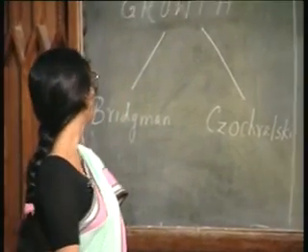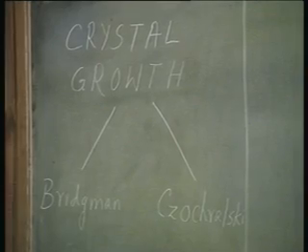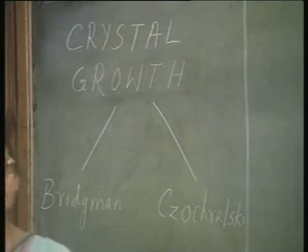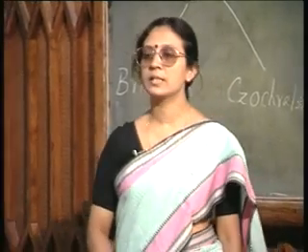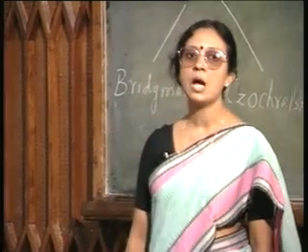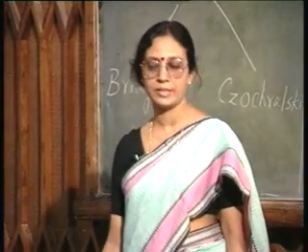And the crystal growth can be broadly classified as Bridgman technique and Czochralski technique. Let me at the onset tell you that most of the silicon that is commercially available today is grown by the Czochralski technique and sometimes further purified.